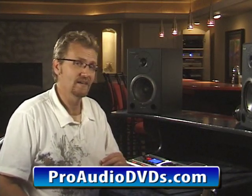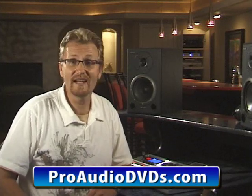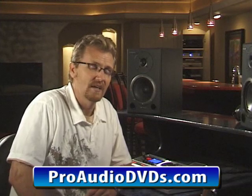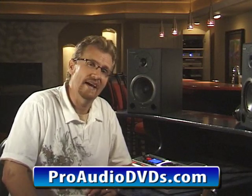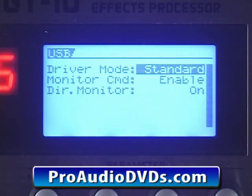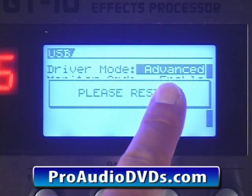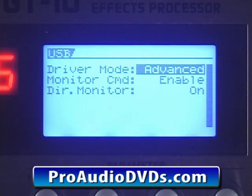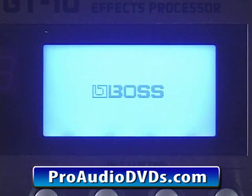A better way to go would be to download the latest advanced driver directly from your local Roland website. Install that on your Mac or PC and then set up your GT-10 to use that advanced driver. Press System, USB, and Enter. Now we'll select Advanced mode, and as we can see on the screen here, we'll need to restart. So I'll cycle the power.